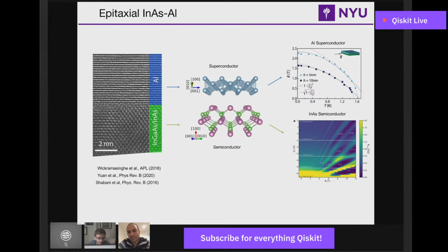If you put that layer of aluminum arsenide, then basically each layer grows differently. Aluminum grows in a 1-1-1 direction. It's like a van der Waals material. It can take a lot of strain, so it's really kind of decoupled from the substrate, which is the indium arsenide, once you can get it to that phase. In this picture of these heterostructures, you would have this diffusion barrier of less than a nanometer. Yes, a monolayer or two, which is the key basically.